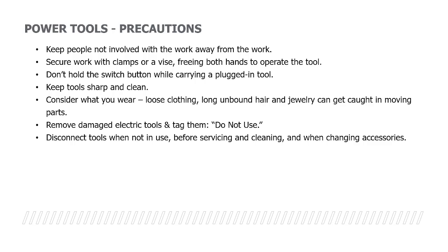Power tool precautions. Keep people not involved with the work away from the work area. Secure your work with clamps or a vise, freeing your hands to operate the tool. Do not hold the switch button while carrying the plugged-in tool. Keep tools sharp and clean. Consider what you're wearing. Loose clothing, long unbound hair, and jewelry can get caught in moving parts.